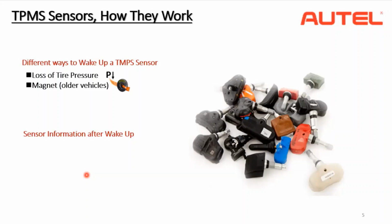Another way to wake up the TPMS sensor is by sending a 125 kilohertz radio frequency to the TPMS sensors. This is basically carried out by using a professional TPMS tool like the Autel TPMS tools, which sends a radio frequency of 125 kilohertz to force the TPMS sensor to get active. That's how we usually trigger the TPMS sensor to get the TPMS sensor data.